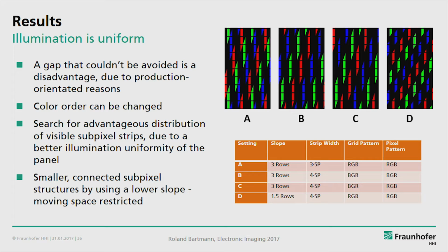And also there is the slant angle of the color filter stripes, and we can alter that angle, and then with a lower angle we will get the solution D, and it's really nicely distributed. The colors are really nicely distributed here, and you will get a good white balance.